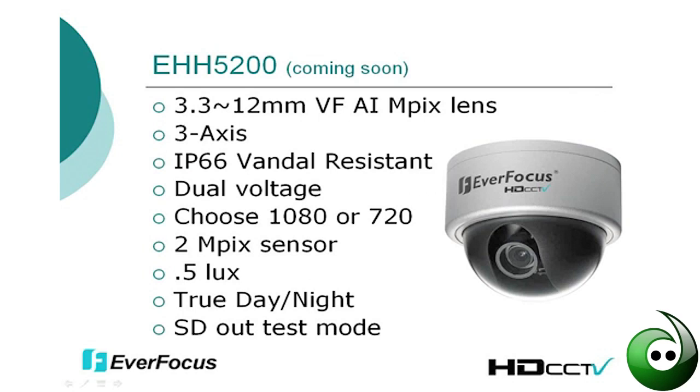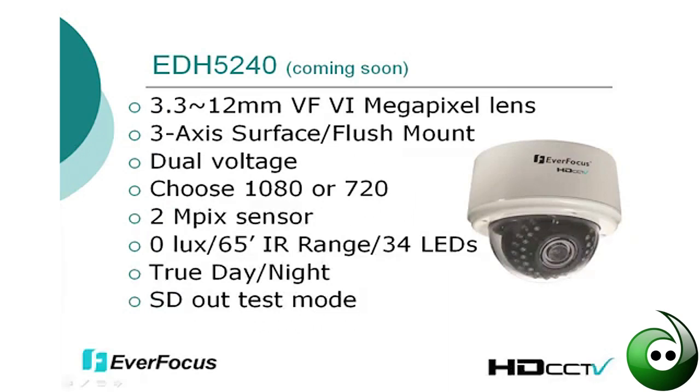Coming soon is our 3.3 to 12 millimeter varifocal auto iris megapixel outdoor dome with 3-axis mounting. It is an IP66 vandal resistant dome, dual voltage, dual resolution, 2 megapixel sensor, 0.5 lux sensitivity, true day night, and also has the standard def test output. The EDH5240 also has a 3.3 to 12 varifocal auto iris lens. It is a 3-axis housing that can be surface or flush mounted with the same housing. Discard the back can and you can mount the camera flush with the surface.